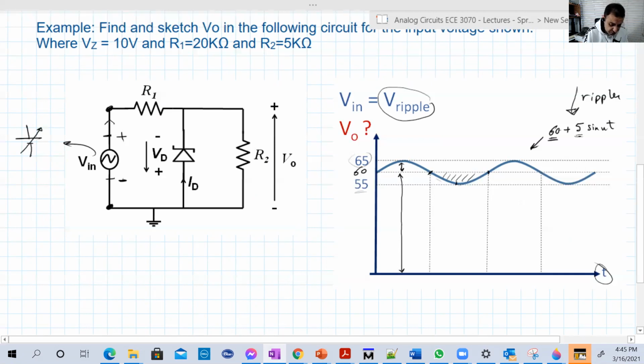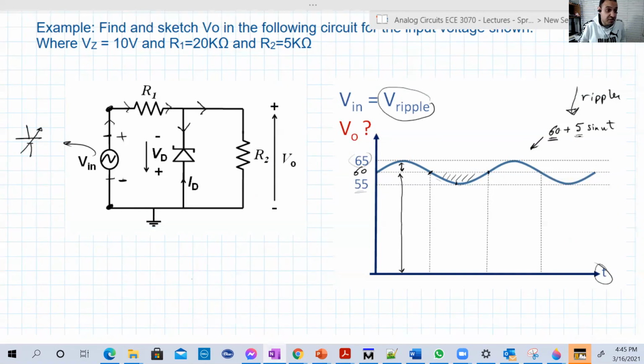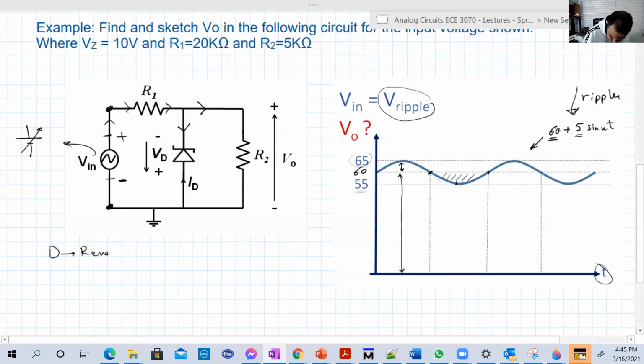With this battery, you want to inject the current in that direction. This current will go through R1. Then it's going to go into two branches here. So the positive current in the diode should go from N to P, which is basically reverse. That means reverse, because no positive current can flow in that direction. In forward, of course, but in reverse, no. Okay, good. So basically, the diode is reverse. The zener is reverse here.